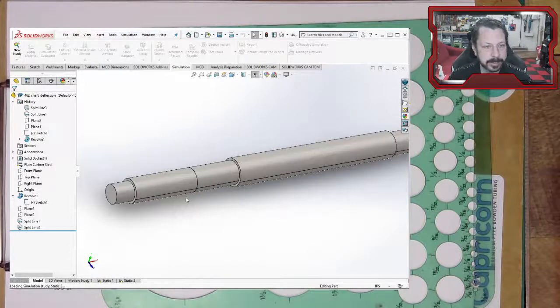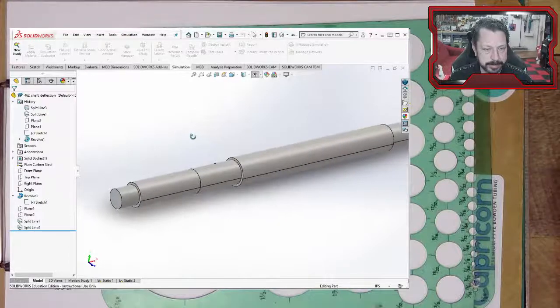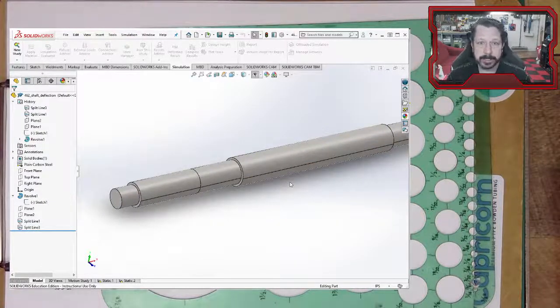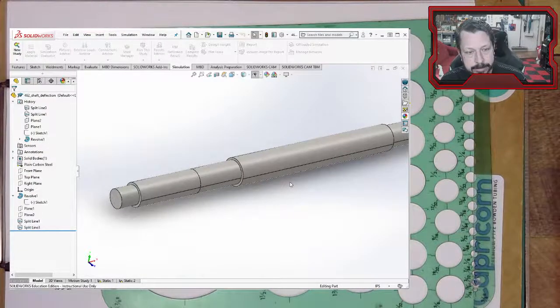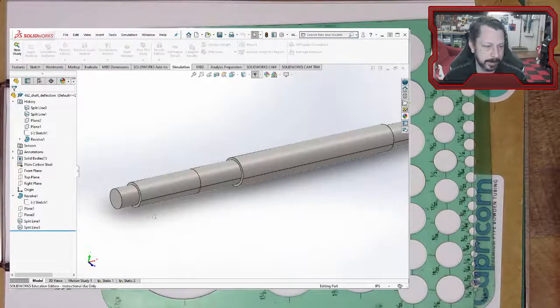Maybe those gears didn't actually show any sort of retaining mechanism at all. They don't have a set screw. I don't even think they had a key in them for torque transfer. So they probably, maybe they're designed for a press fit, but we're not too worried with that part yet. On Monday, we'll talk about torque transfer and elements to locate elements such as the gears and pulleys and all that. We'll talk about that on Monday.